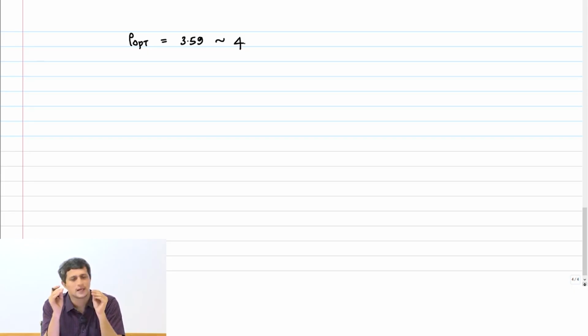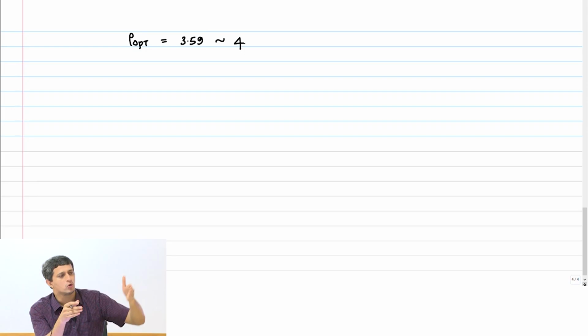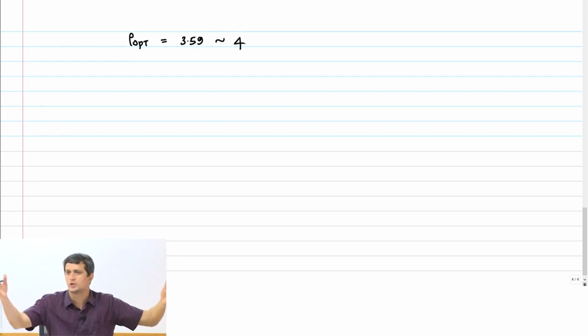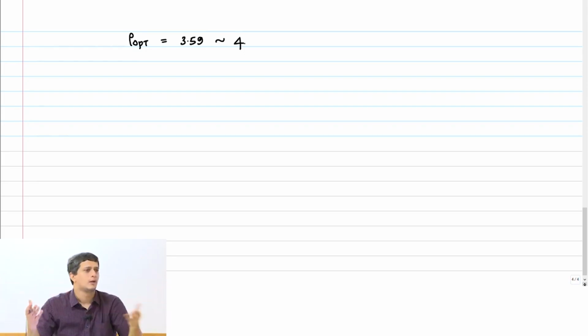So therefore, it's an accepted approximation to make, and that is why you will find this fan out of 4 to be such a magic number in digital design, because that is the optimal stage effort that is going to give you the minimum delay. So if I want to send one signal from here to there and I want to buffer it, then what would I do?